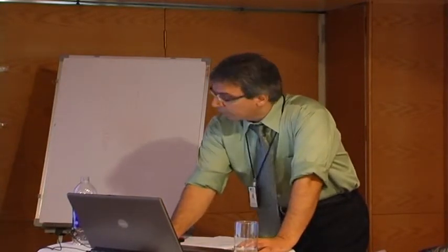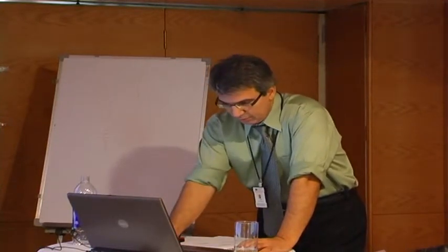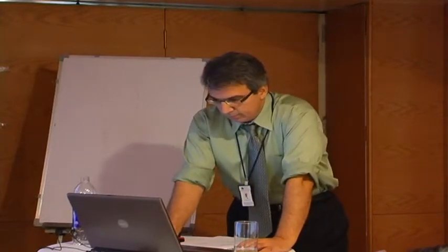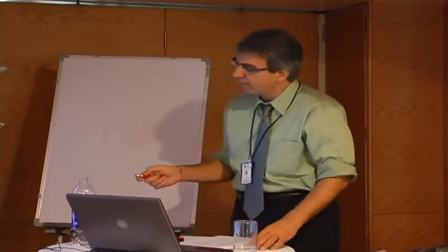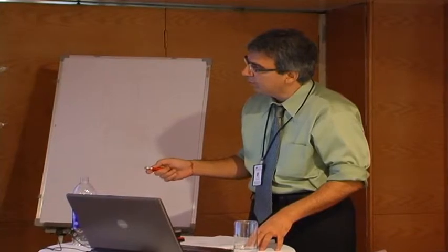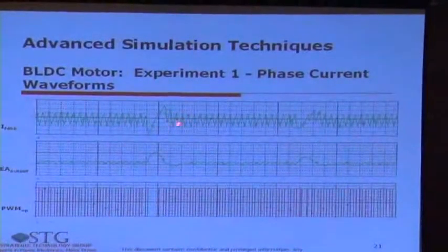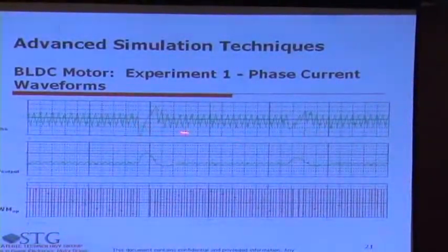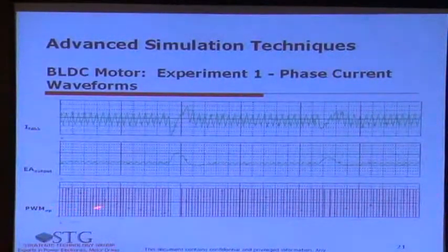So here are three waveforms which we got from the simulation, and the current seems pretty decent for this particular motor. 20 kilohertz, 242 microhenry seems like a decent target for high side PWM. This is some more waveforms to look at. We have the I feedback. Now we have these dips within the I feedback. This is obviously when we have a transition, basically 6 times a cycle. We have the error amplifier output, and then we have a PWM output.